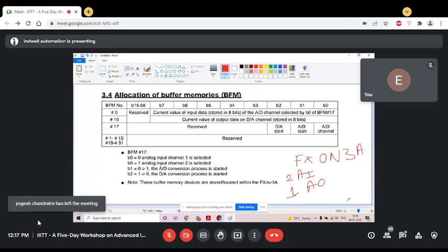1 analog output channel. Got it? So on this module, we have two analog input, one analog output channel here. It takes power supply from PLC itself, but many modules will require 24-volt DC to get power on. And here you can see we have the bus which we connect to PLC extension port.